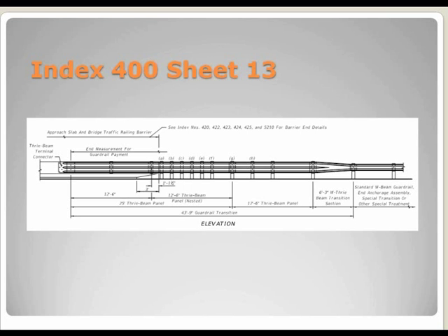The entire length that's calculated is going to be the length where it attaches to the bridge traffic railing barrier and measures all the way to your end anchorage at the end of the guardrail. The entire length is one length, and it's summed from that begin station to the end station, and it's all included in the cost of the parent guardrail. And in this case, the parent guardrail is the standard W-beam guardrail.